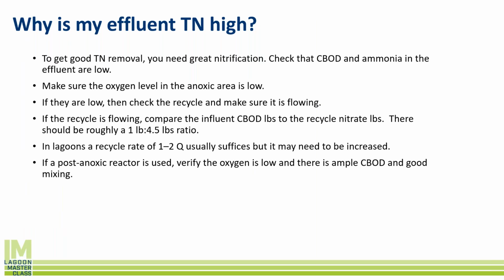In lagoons, typically a recycle rate of 1 to 2 times your flow is really going to suffice. So if you're getting 100,000 gallons a day, recycling 100,000 to 200,000 gallons a day is usually going to be sufficient to do that nitrification.